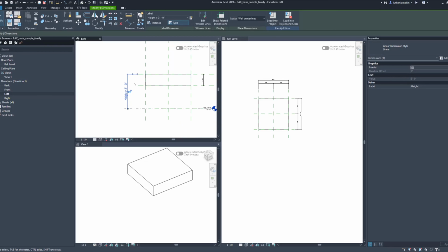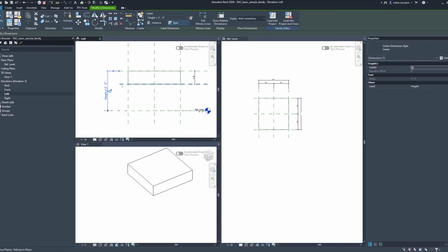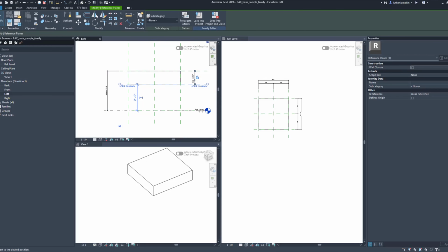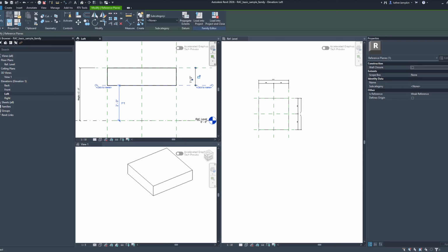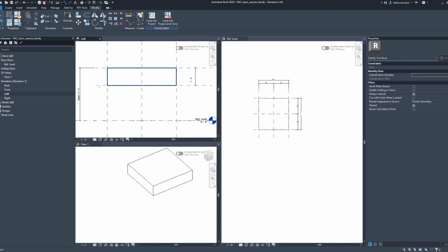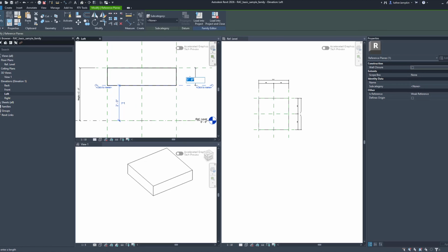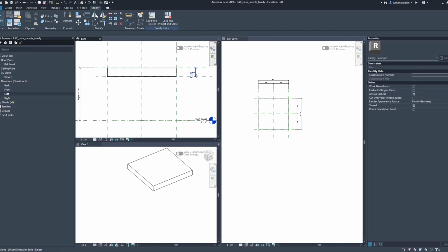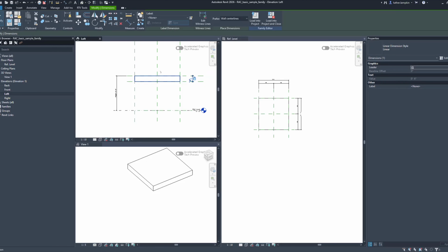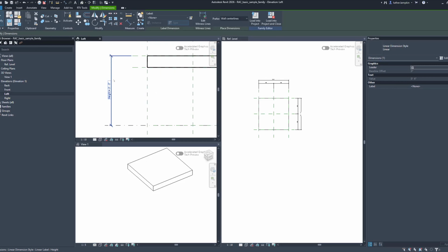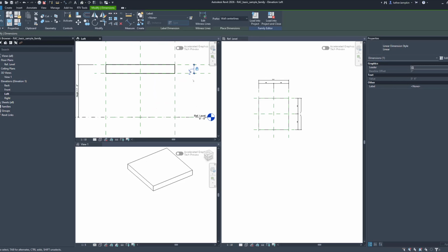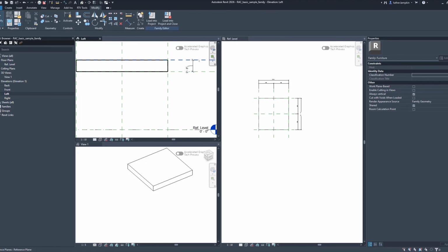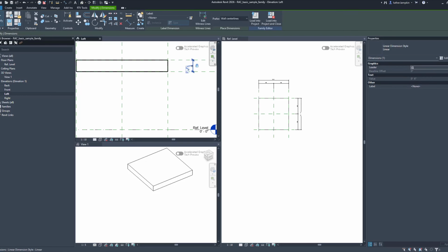Now, when we're doing this family, and you see the part that we have right here, remember we locked everything before, so I'm going to change this lock. Let's go on this line again, and I want this to be 6 inches. Now I want that to lock again. So now that's going to be 6 inches for the base. Right there, boom. Now, if I need that number turned into a parameter, I'm going to show you how to do it here as well.